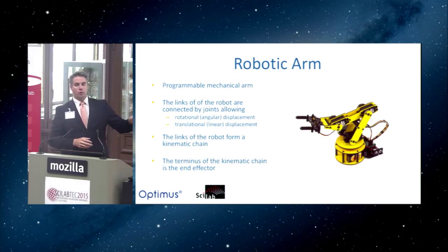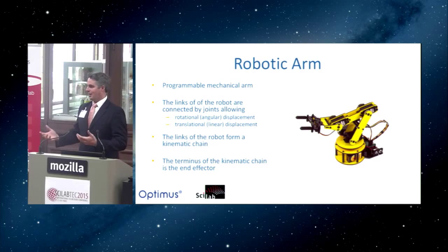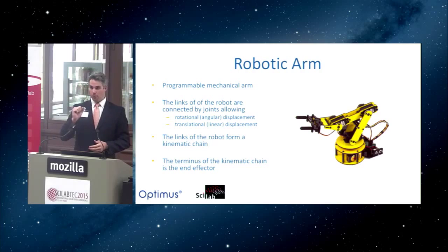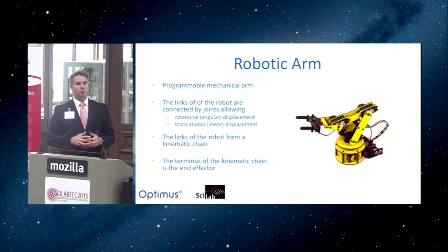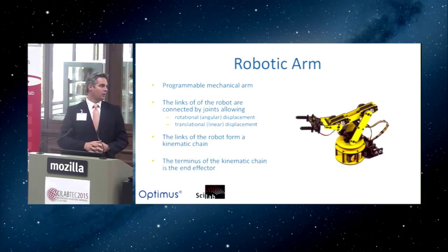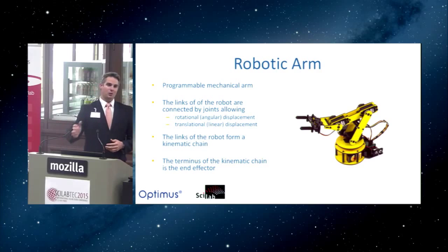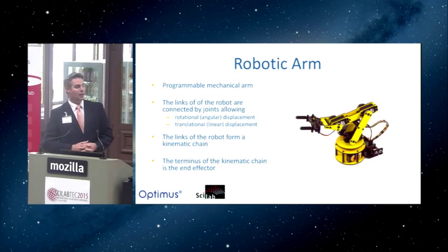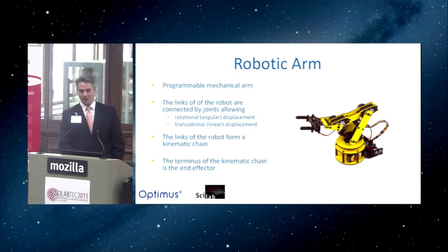When you're driving these arms, you give it a command. You say to the arm, this is where I want you to go. The servo motors then do their best to begin moving, feed some data back and say, hey, this is where I'm at this millisecond, this is where I'm at this millisecond. And of course, just like maybe with your arm, sometimes there's a little bit of overshoot, and so you have to bring it back a little bit, and you end up in this process until you end up exactly where you need to be. Of course, with our brains, we do it instantaneously. It's not a problem. In the mechatronics world, it takes a few hundred milliseconds to do.